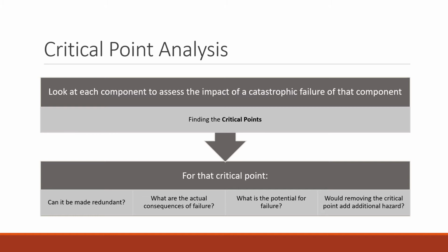Then we can also look at what are the consequences of failure. So, okay, this one anchor that gives us a change of direction and makes it easier to pull the rope, if that fails, what actually happens to the system? The rope jogs a little bit over and load changes briefly, but nothing happens, no one falls, etc. The belay system's still good, no big deal.